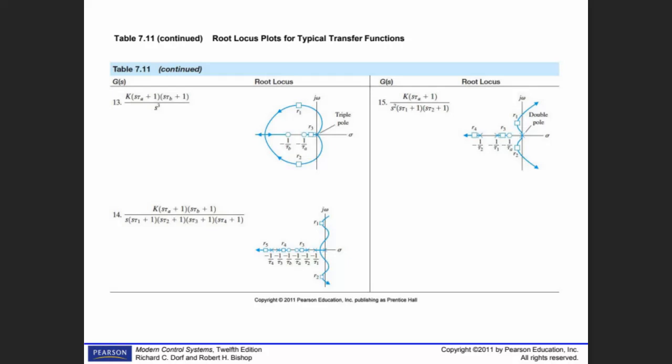That part is important since it is very near to the j omega axis. The other parts are recessive poles. The effect of these poles is not important, but here it is. So for k equals 0, that one and that one. When you increase k, the curve is moving. But stop here. Don't increase further. If you increase further, it is going to be oscillatory.